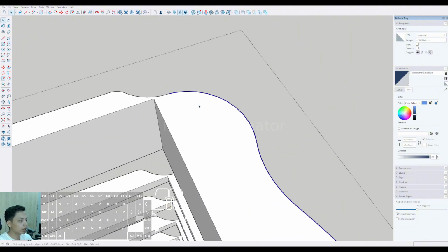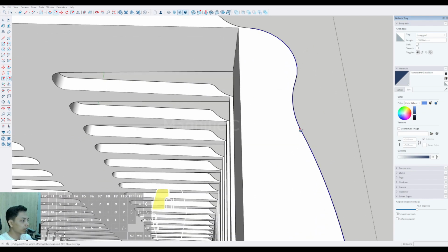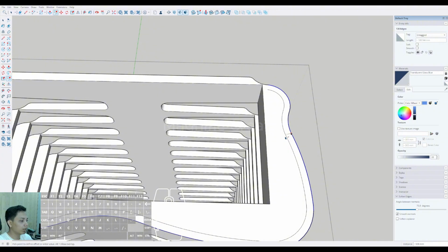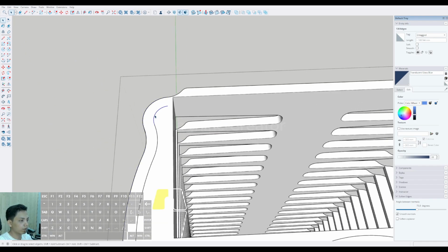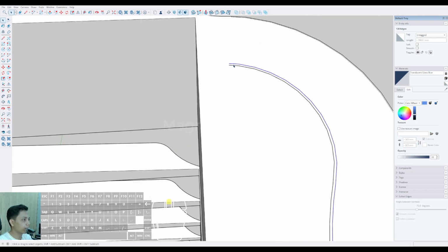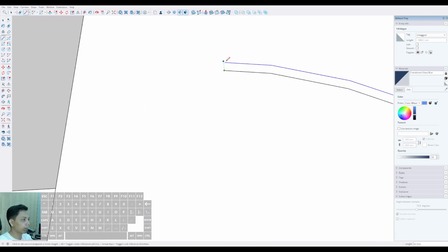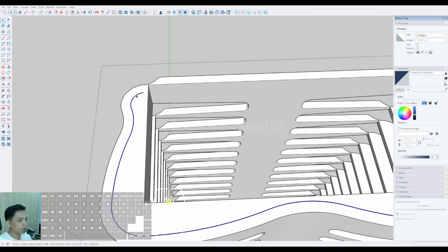Okay, now we have to offset it inside again. We can offset it inside around 1.5 meter. Okay, well, now we can get the outline of this railing, glass railing. Then we have to offset it inside again around 50 millimeter. So this 50 millimeter value is included with the frame, glass frame anyway.